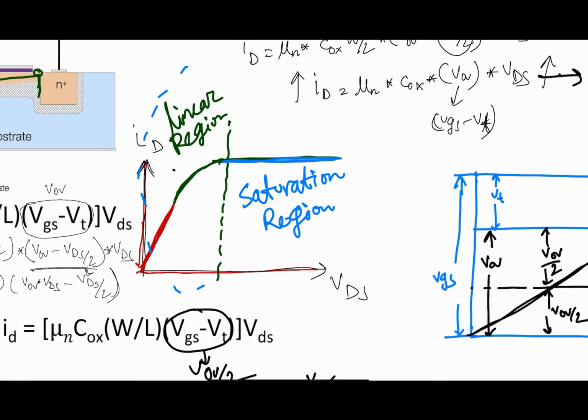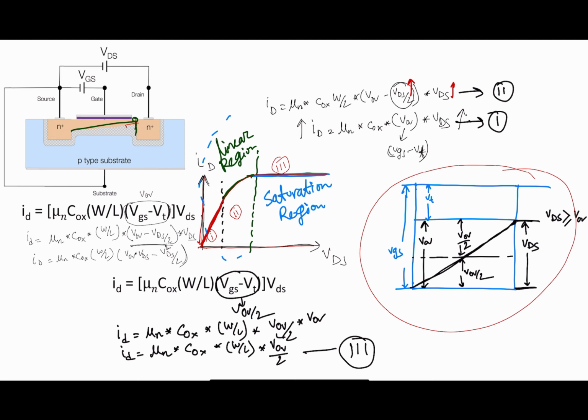So this is the whole concept of the MOSFET current, how the channel is formed, how the channel is tapered, and what the value of the current is in the saturation region. In the saturation region, the channel is pinched off, but the current is not zero. Keep that in mind. We need to find the voltage or current with this diagram.